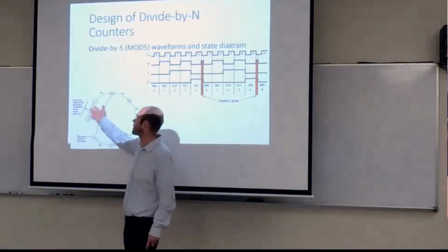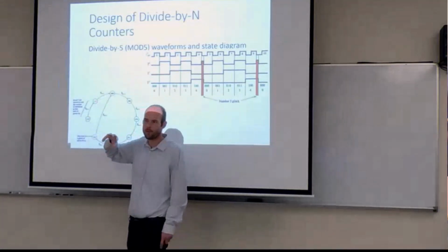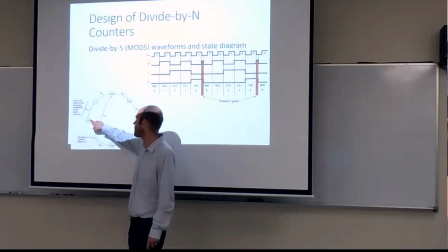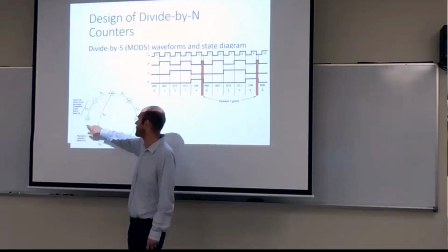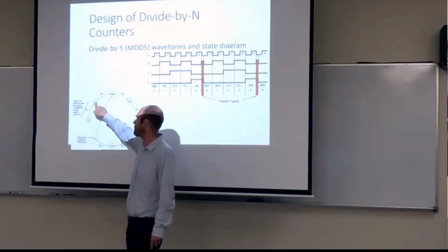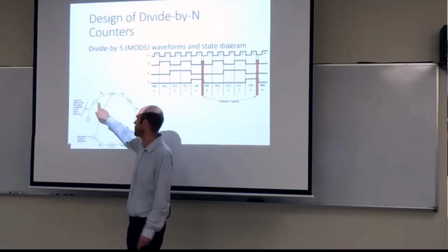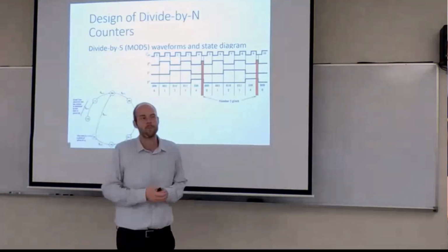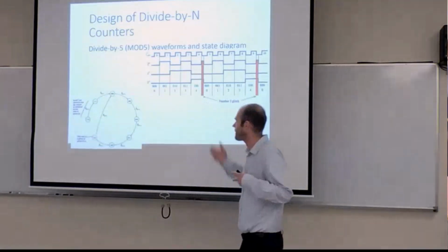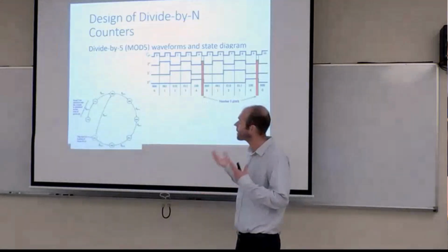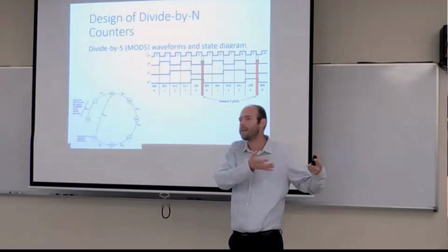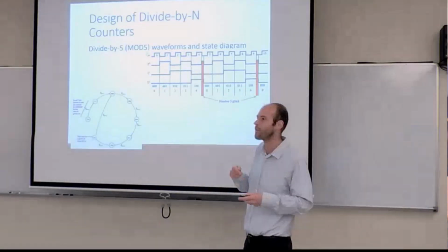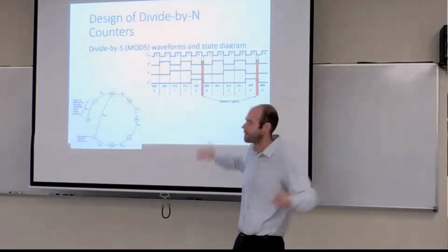6 and 7 are shown in case there is a power up state, where those happen. If you started at 6 or 7, your circuit would continue to count, but then it would hit reset actually at 111 if we were looking at those outer 2 bits, and jump to reset and then be locked into its pattern. So once we go into design of state machines later on, we do have to consider if we're outside of the flow of where we want to be, does it get back on track? Or does it just count off into infinity somewhere else?